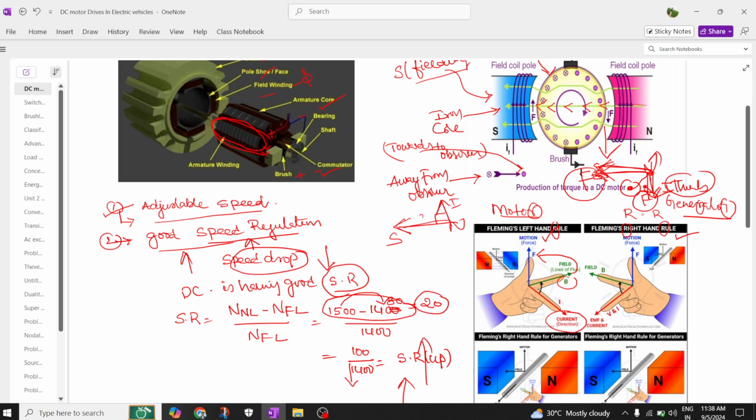Here it is maintaining 90 degrees, and you can see the force experienced is in the upward direction. So this side is trying to move in this direction, and this side is trying to move in this direction. Automatically a twisting force is produced, which is called torque. Very simple to understand; you can understand this only when you physically see it. In this, the thumb is in this direction, the force will come in the downward direction, and the center finger will be facing you.